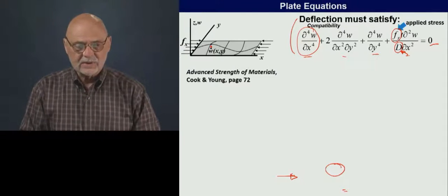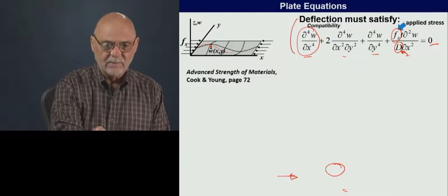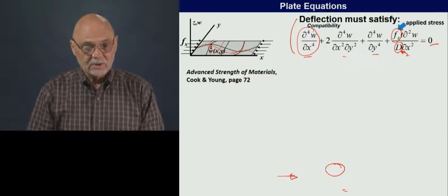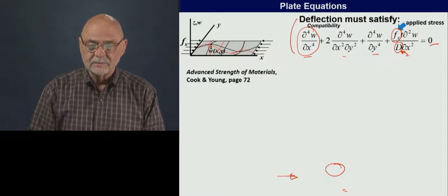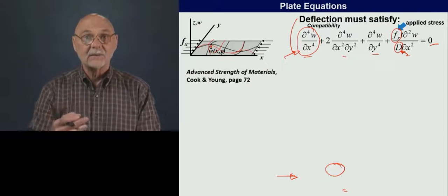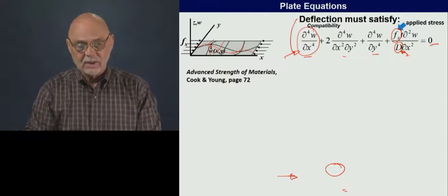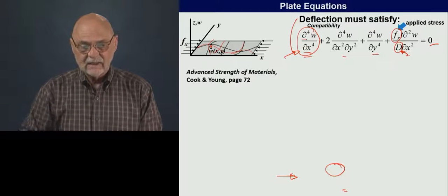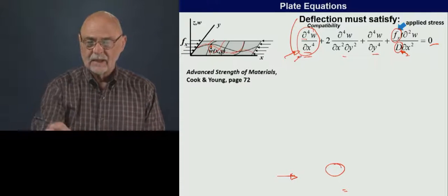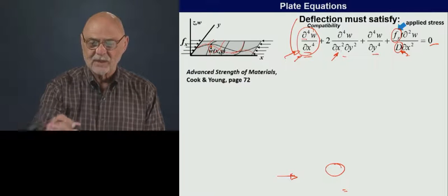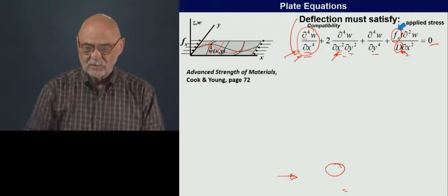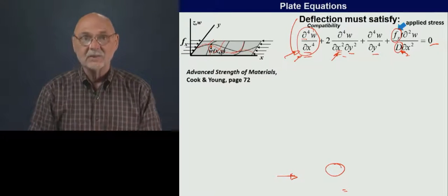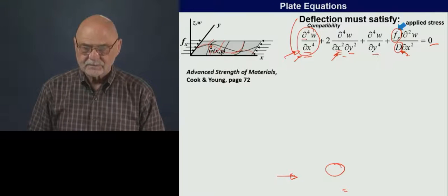We have a bunch of derivatives. What this is saying is that this plate is going to be buckling in some shape, W. We have a two-dimensional problem here, so W varies with both x and y. If we guess at a W function like we did with the buckling beam, we take 4 derivatives of it with respect to x for this term. With this term, we take 2 derivatives with respect to x of that W function, and then 2 with respect to y, and multiply it by 2, etc. So we're really just taking derivatives of a function.